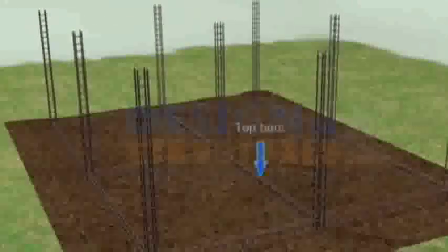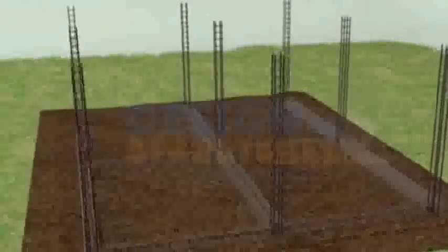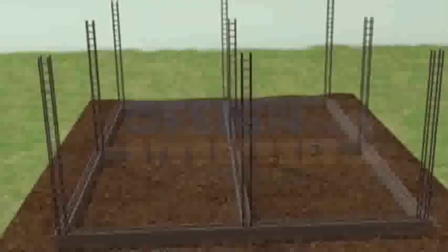Backfill with soil. Backfill provides stability to the building. Plinth beams and foundation. Beam reinforcement shall be as per drawings. Top bars, bottom bars and stirrups to be placed with proper development length. Joints in the beam shuttering should be tight against leakage of cement grout. Construction of shuttering should permit removal of various parts in desired sequences without damage to the concrete.